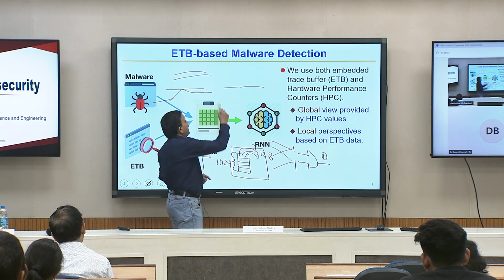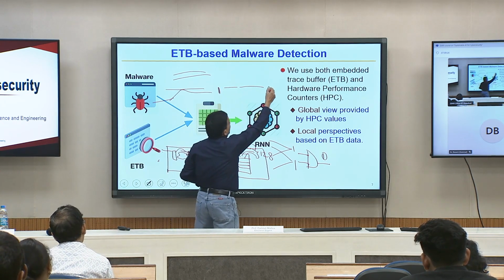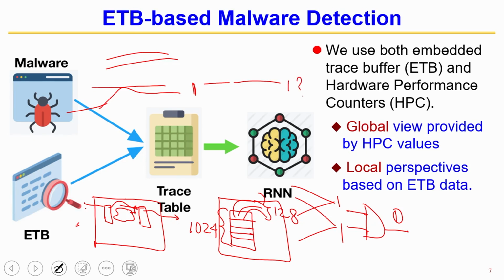How do I test it? I put a 1 here and I see if I get a 1 here. To do that, I have to initialize all these flip flops, then I put a 1 and then I check for 1. So, wire by wire, for each of those millions of wires I have to test.